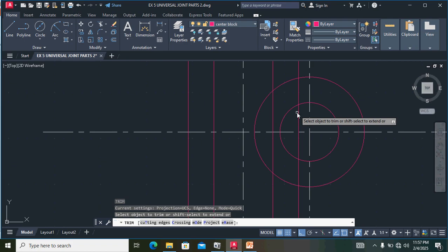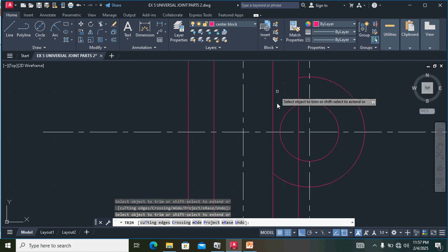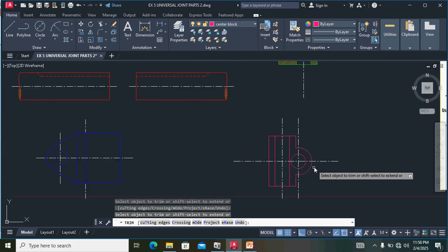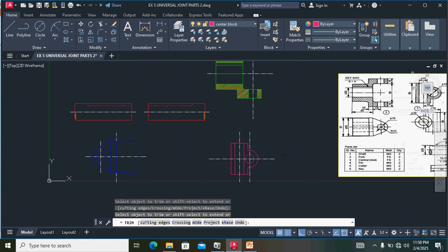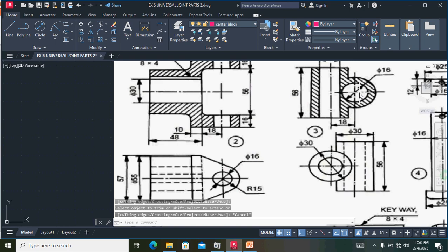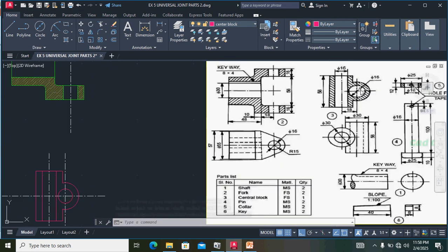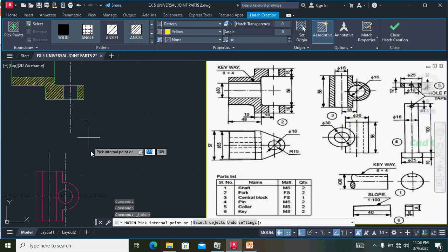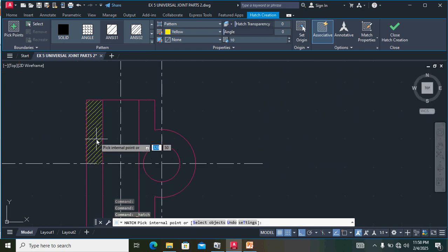So in this case, we have to draw a center line. Draw one center line from this point to this point. Select the layer center, draw a line. Here I want to use normal line, by block. So we select a line from this point and approximately draw. Okay, click enter. Just click the line and this point to this distance. That's all. This is the center line.